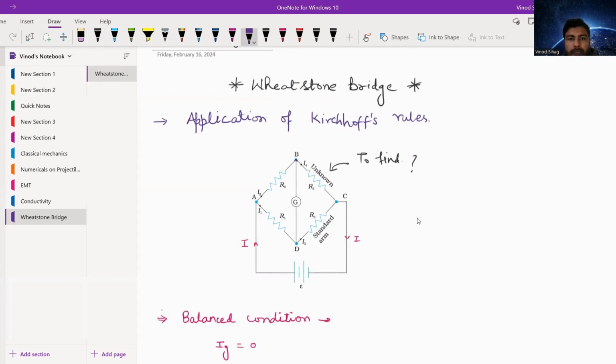Okay. So as per the junction rule, we know that the currents entering the junction and the currents leaving the junction will be equal. So here there are only three arms, the vertical and these tilted arms. Here we can see that the current I2 is coming to the junction and current I4 is leaving from the junction.